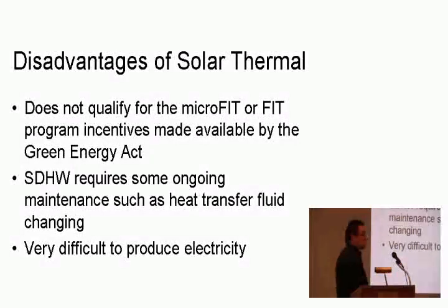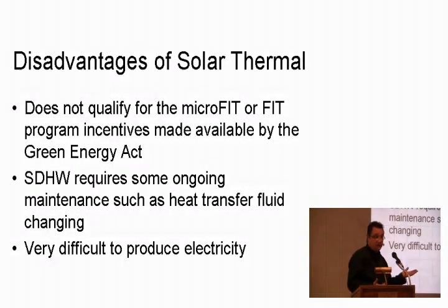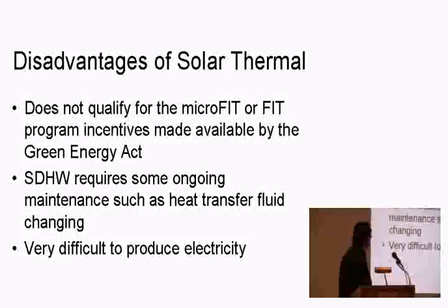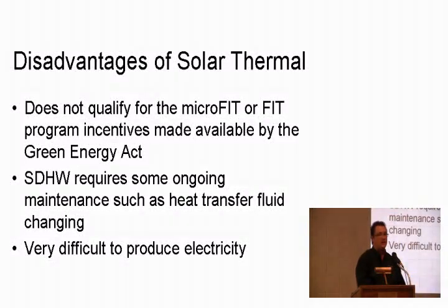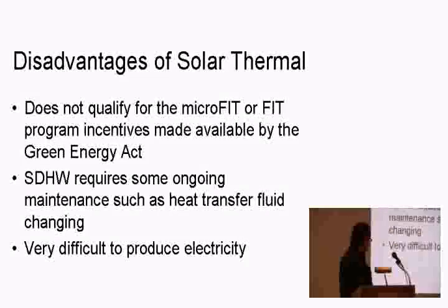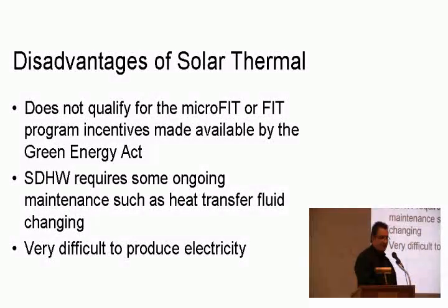The disadvantages of the solar thermal right now, if you've heard of the microFIT or the FIT, solar thermal does not qualify for that program. Secondly, solar thermal requires some ongoing maintenance. After a number of years, you will have to check the fluid, change the fluid, etc. And the last one there is that it's difficult to produce electricity. There are some commercial systems that they're experimenting with that will produce electricity.